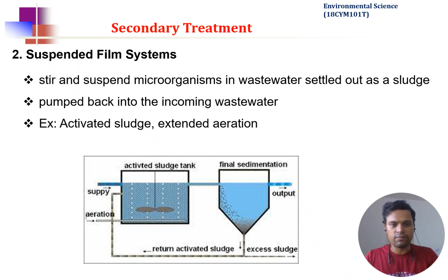Now this is the suspended film system, which is basically the activated sludge process. Here you can see we have an aeration tank, and you can have a blade which can infuse a lot of oxygen into the wastewater, which will contain a lot of microorganisms or bacteria. These bacteria will have enough time to consume or decompose all the organic material. This is a very important step, and the retention time will change based on the amount of waste you have in the wastewater.